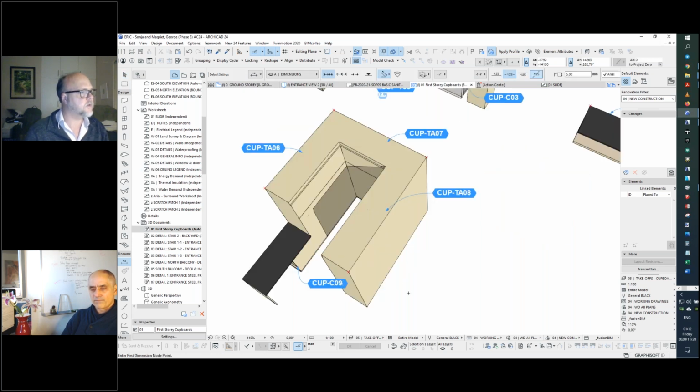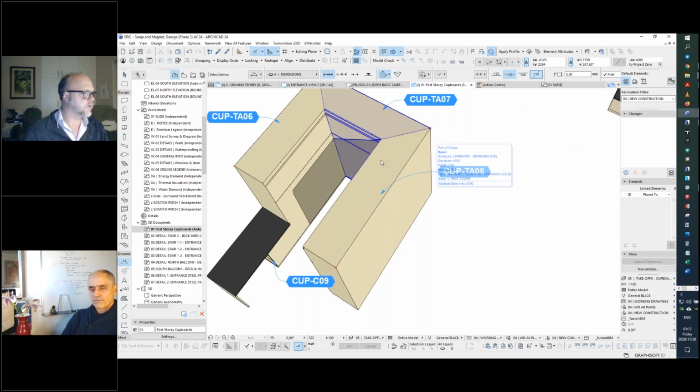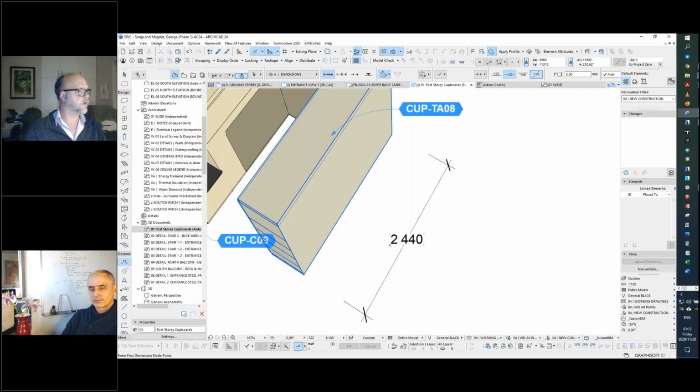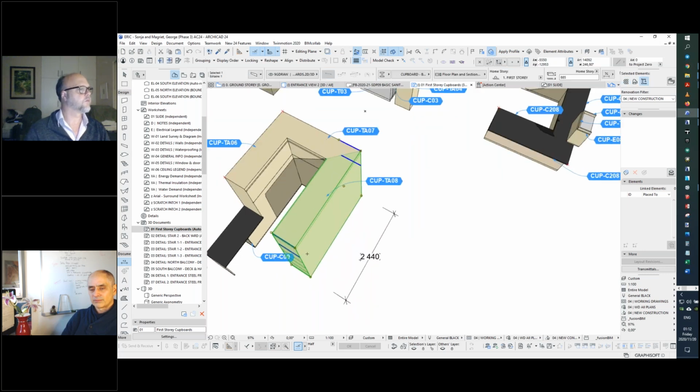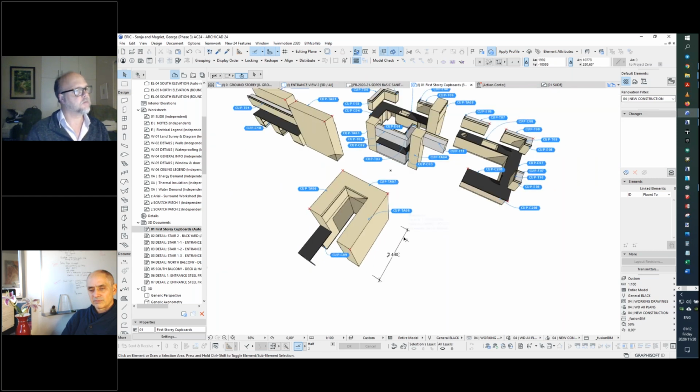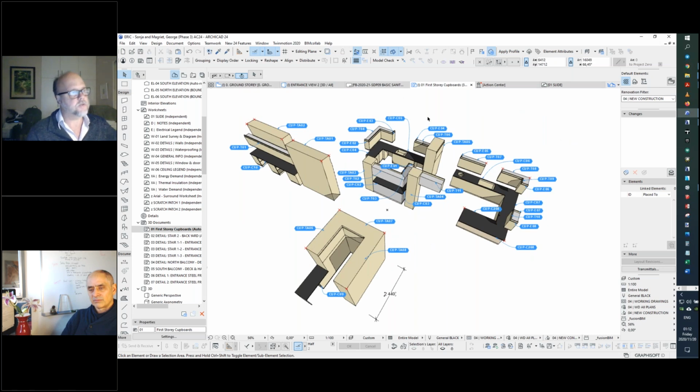Now you can dimension to the actual 3D cupboard. At the bottom of this cupboard, there's no hotspots. So I can, let's just dimension that. So putting in the little X's, the hotspots, is optional. You just did that as a visual touch? Yeah, no, I was doing some dimensioning on here, and then I ended up removing that dimensioning. I didn't clean up the hotspots. So I opted to call out the dimensions of these units in the schedule at the end. Right, but why did you put the hotspot X's? Because you can dimension to the node points without having the hotspot. That is correct.